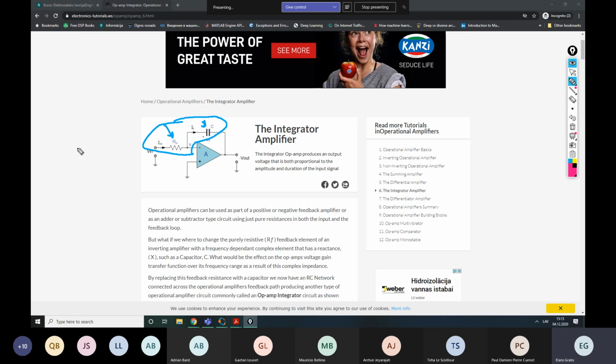So, for example, consider that you are sending some zeros at the start and then some 1 volt level. What will happen at the output is that after we start sending the 1 volt value, it will continuously rise. And here we need to stop this rising and reset this integrator and read the value calculated at the end.